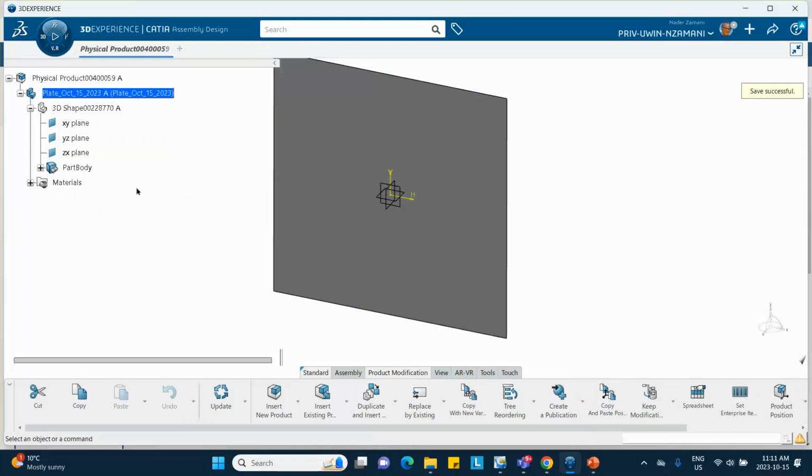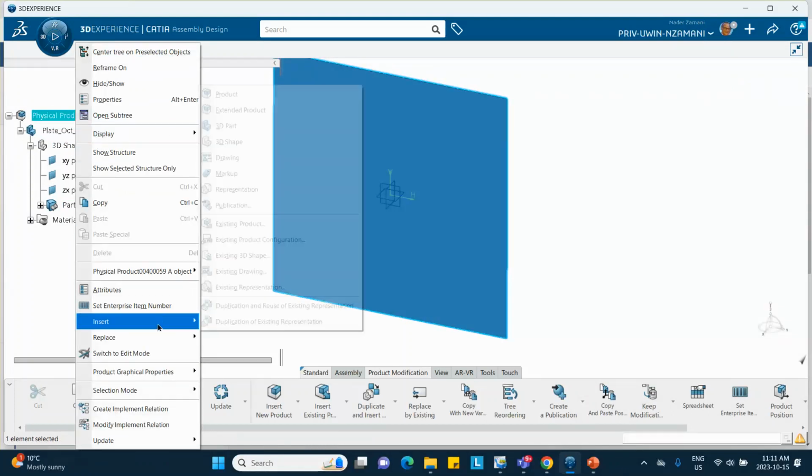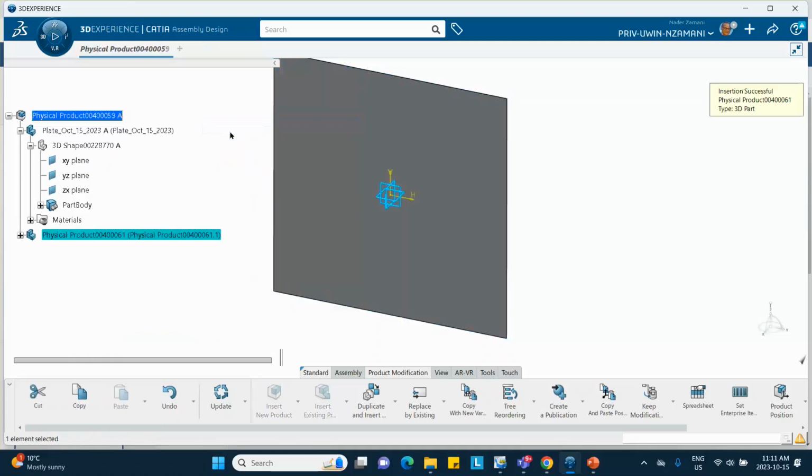All right, so now we're going to go to the meshing. I don't have to insert the sphere. I have to do the sphere right there. So we go all the way to the top, right click, insert 3D part. This is going to be my sphere, which will be modeled with analytical rigid surface.